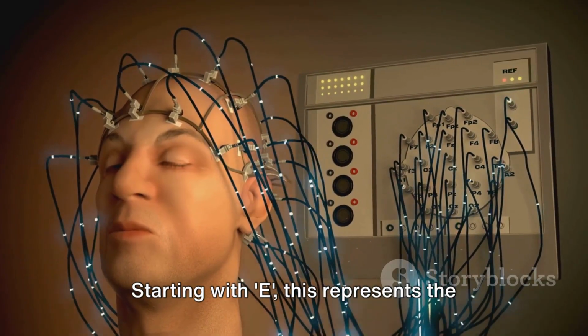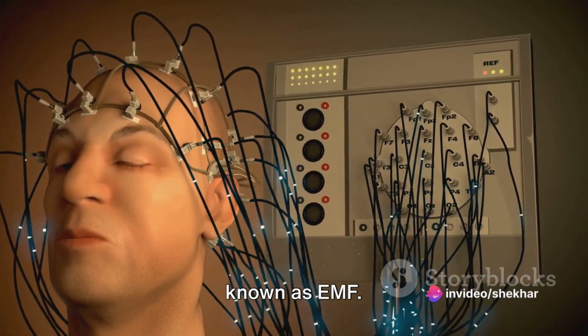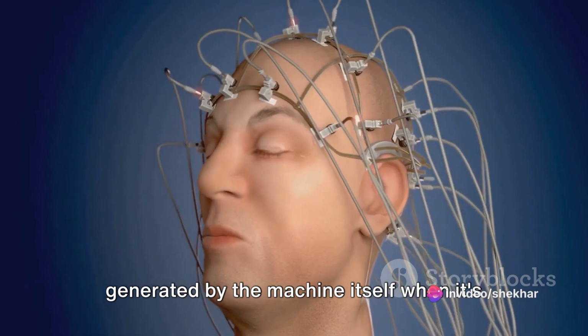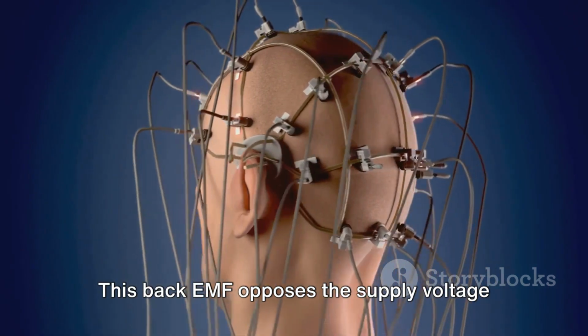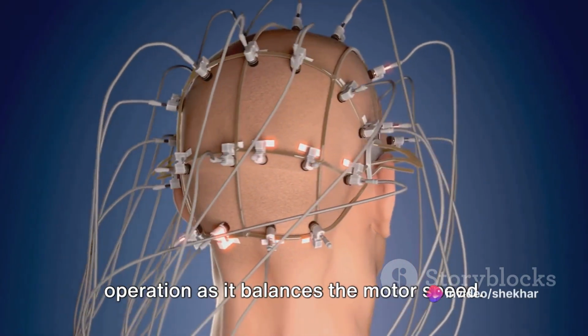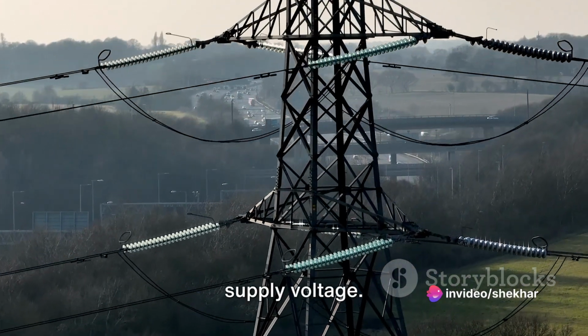Starting with E, this represents the back or counter electromotive force, also known as EMF. In a DC machine, this is the voltage generated by the machine itself when it's operating as a motor. This back EMF opposes the supply voltage and is a crucial aspect of the machine's operation as it balances the motor speed.